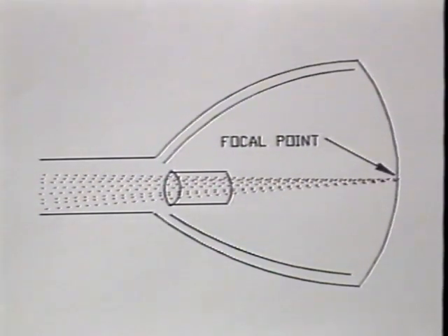This adjusts the voltage on the focusing element so that the electron beam converges right at the faceplate, producing small, sharp pixels. A misadjusted focus control results in large splotchy areas on the screen. Always perform the focus adjustment after the brightness, since changing the level on the acceleration grid affects the beam's convergence point. Once you have completed all of these electrical alignments, you will need to make several mechanical adjustments.